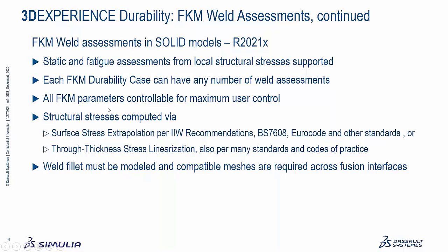Each FKM durability case can have any number of weld assessments. So we have an assessment concept that's basically like an Abaqus step, though it's not so sequentially evolving as you have in Abaqus. They're basically independent assessments, but it allows you to do a lot of assessments all in one job submission.